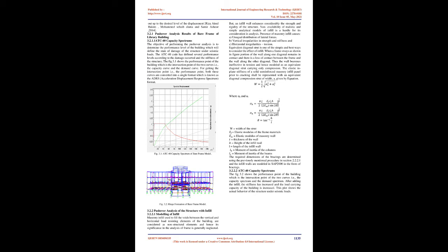The modeling and analysis was carried out first in SAP 2000. Modeling consisted of the following steps. 2.2.1 Structural discretization. The beams and columns layout were available. Then the structure was discretized. Discretization includes fixing of joint coordinates and member incidences. 2.2.2 Property specification and support condition. Properties were assigned to the members. The member properties were given. Then support conditions were given to the structure. The support condition given was fixed.